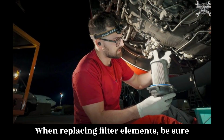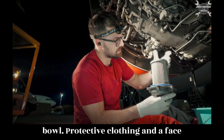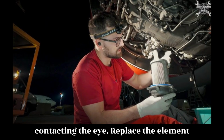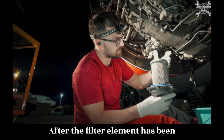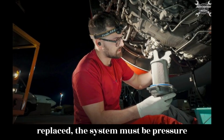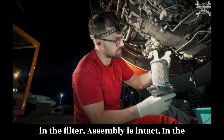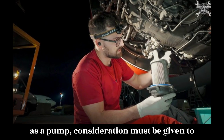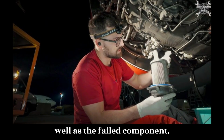When replacing filter elements, be sure that there is no pressure on the filter bowl. Protective clothing and a face shield must be used to prevent fluid from contacting the eye. Replace the element with one that has the proper rating. After the filter element has been replaced, the system must be pressure tested to ensure that the sealing element in the filter assembly is intact. In the event of a major component failure, such as a pump, consideration must be given to replacing the system filter elements, as well as the failed component.